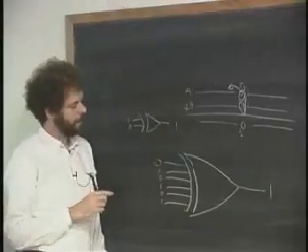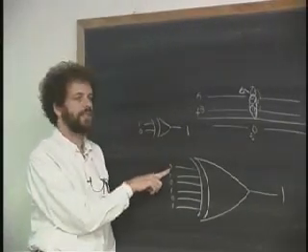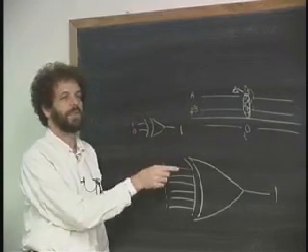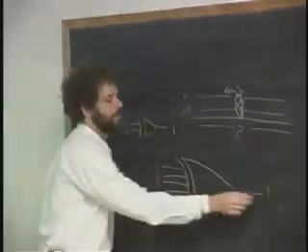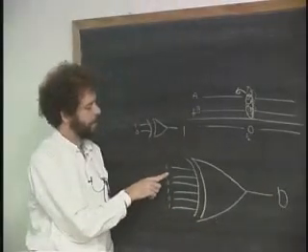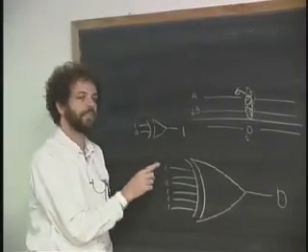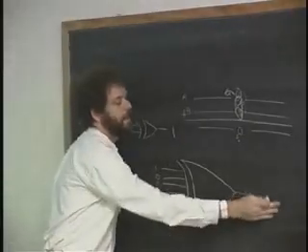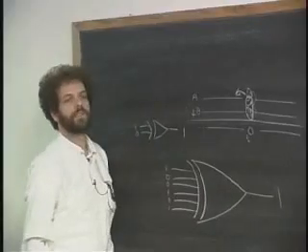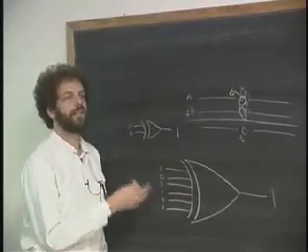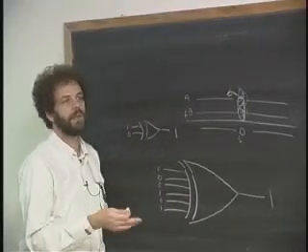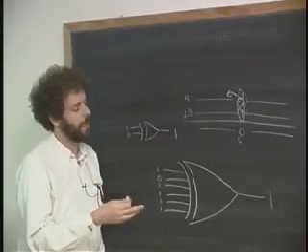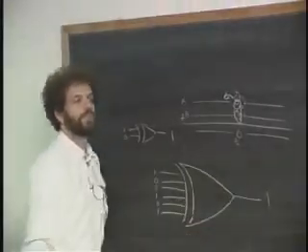But look at what takes place here. What happens if I change any of these bits? If I change this one from a 0 to a 1, what's the output going to do? Switches from 1 to 0. And in fact, it has this great characteristic that it is sensitive to a change on any single input with a flipping of the polarity of the output, because it's checking for oddness or evenness, and whenever you add a 1 or subtract a 1, if it was odd, it switches to even. If it was even, it switches to odd, so the output will change from a 1 to a 0.